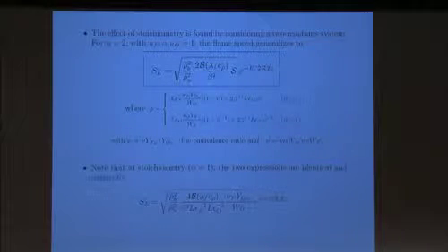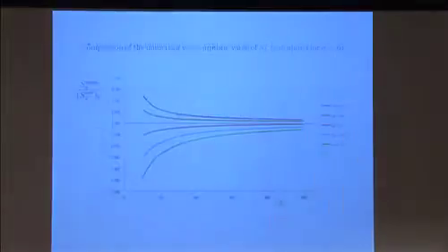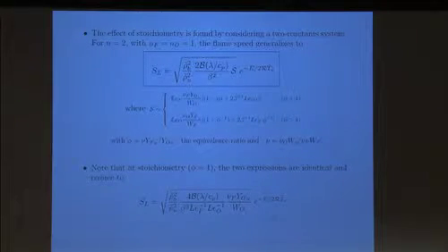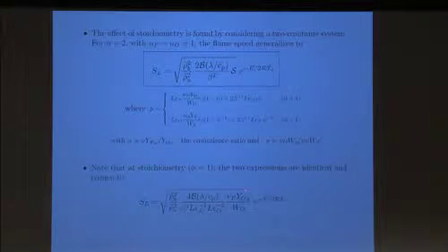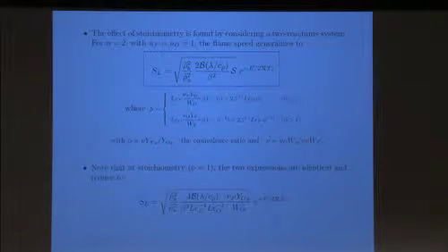The difference between the expression for a single reactant and this other relation can be seen also by the fact that instead of the Lewis number of the deficient reactant, which appears in this expression, two Lewis numbers now appear, both the fuel and oxidizer, at stoichiometry. When you are not at stoichiometry, then one or the other will weigh more, and you can verify it. I am going to move on from here.